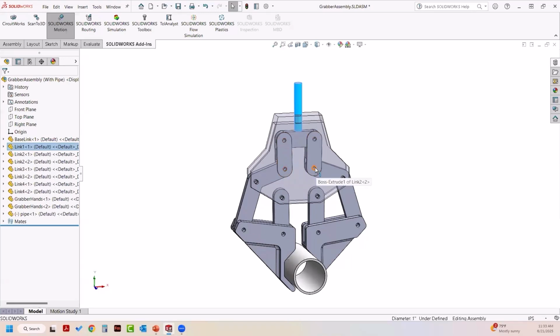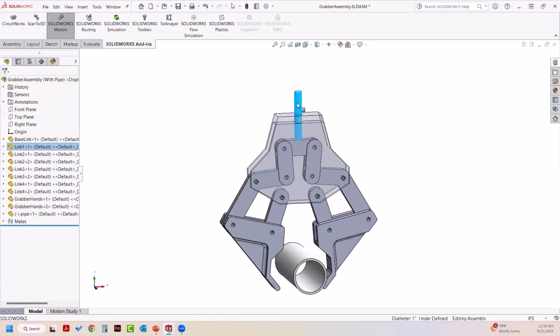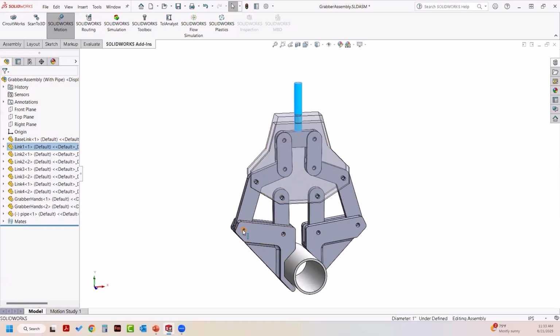And the same will be true on this side because this is a symmetrical system. This pin right here will be represented using a fixture, and this pin will allow rotation because these systems rotate. And this pin will also allow rotation, but no translation. That gives an idea of the setup that we're going to apply to this particular part.